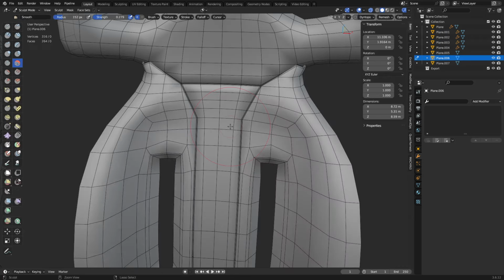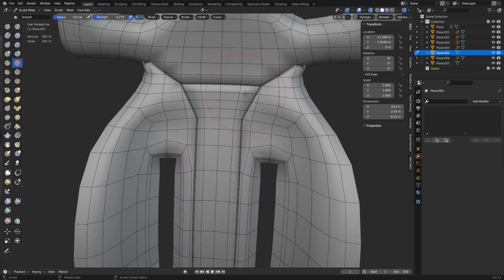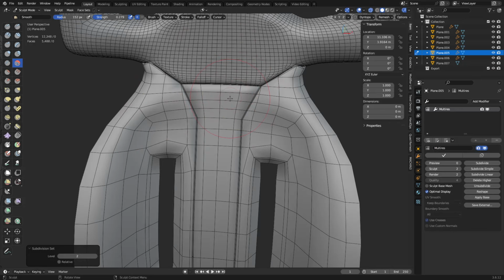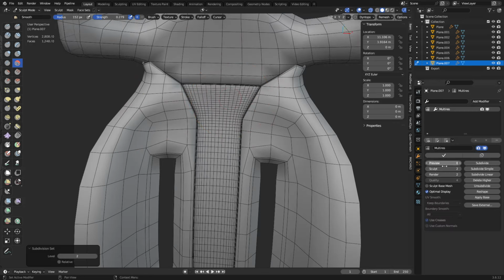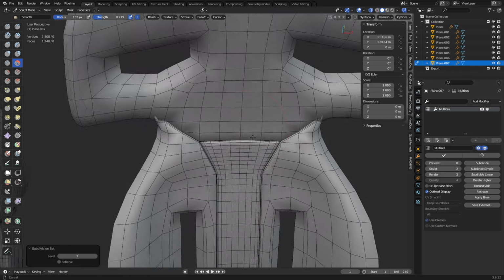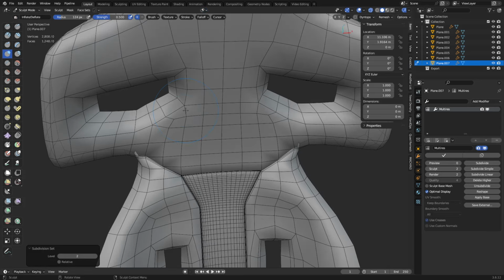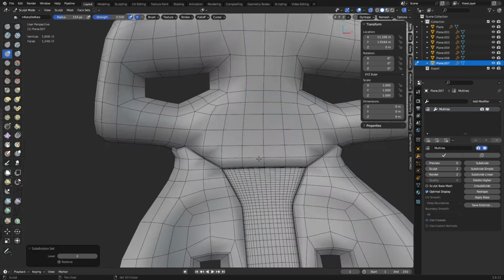If we go into sculpt mode and hit like Control 2, make sure you have no subdivision. Alt Q, you should be able to switch between objects and hit Control 2. Okay, Alt Q, Control 2. You can take the resolution up higher if you want, but just giving you an idea here on how you can work with these meshes. The big one's going to be auto masking, mesh boundary. And you can use anything you want here as far as sculpt tools for the most part, and they won't mess up the mesh boundary. Now, some of the tools I think still do, but usually they don't.